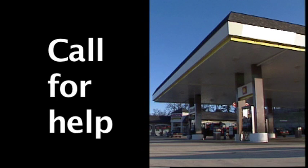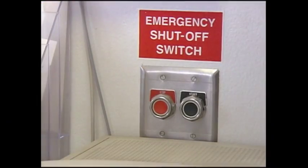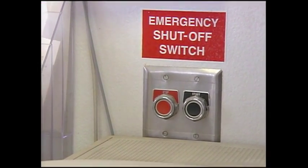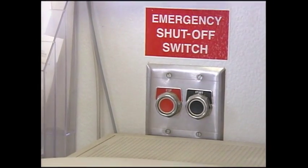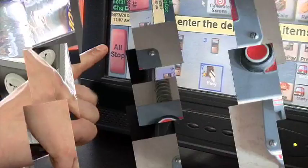Follow their instructions. If a surface release occurs with fuel spilling onto the ground, stop the release, contain the release, and call for help. Every store is equipped with a method for turning off both above-ground dispensers and any underground submersible pumps. At most stores, this can be done by hitting the emergency shutoff switch, which is usually located near the register. You must also know where the emergency shutoff switch is located at your facility.